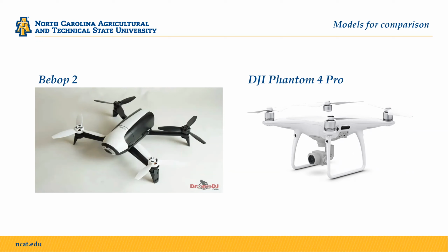The DJI Phantom 4 Pro makes use of orthogonal frequency division multiplexing, or OFDM. Its receiver module is responsible for pairing with remote control and communications. The OFDM receiver implements the Lightbridge technology and is also a middleman between the gimbal and the flight controller. The control signals and video is transmitted over a 2.4 gigahertz range using digital transmission.